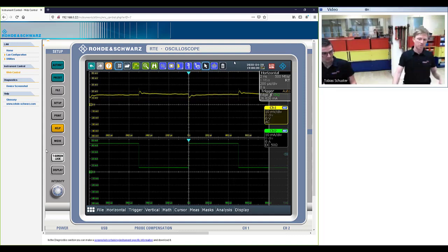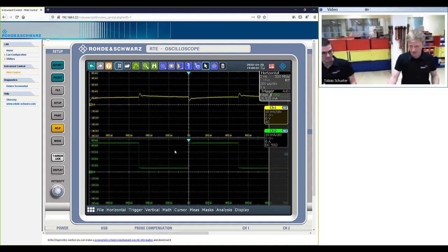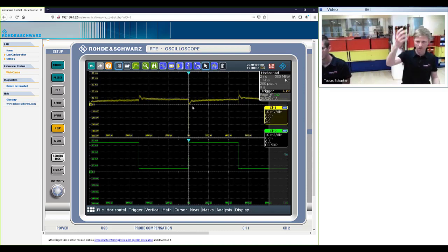So I'm gonna bring on the scope on the screen, and here we can already see on the lower graph of the scope, that's the current steps that we are drawing. So it's 40 milliamps current steps, and on the channel 1 or on the top side we can see the response of the system with the little overshoot and slight ringing. Remember, we have now a setting where we have roughly 30 degrees of phase margin. So that's why we see a couple of rings up there.